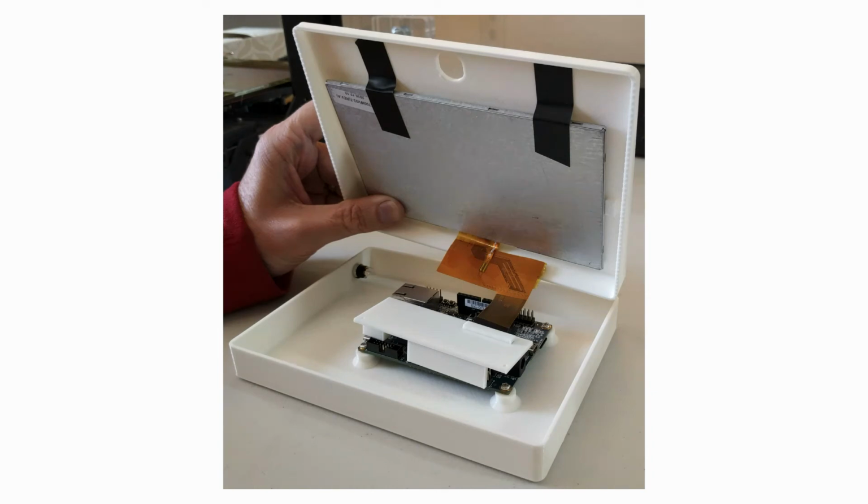And here's something pretty fun. As I was designing all this in Fusion 360, I modeled the daughter board, trying to make sure it was going to pass and the LCD wasn't going to run into it. Because I had it modeled, I could 3D print it. When I put it together, I could put it next to where it's going to be and make sure it was going to fit and not hit any of the other connectors on the dev board.